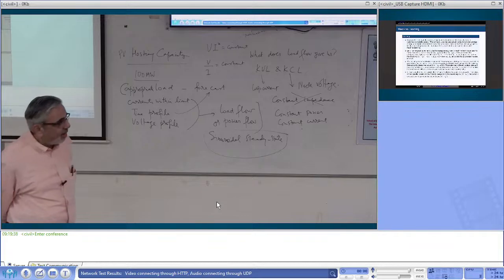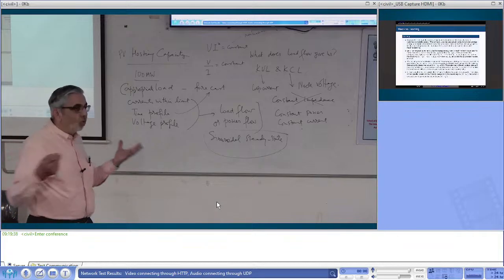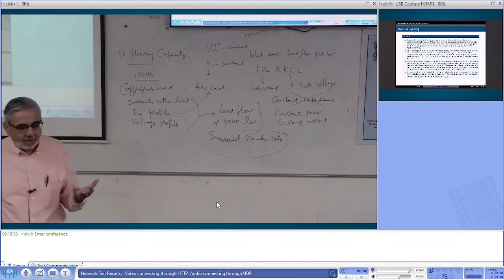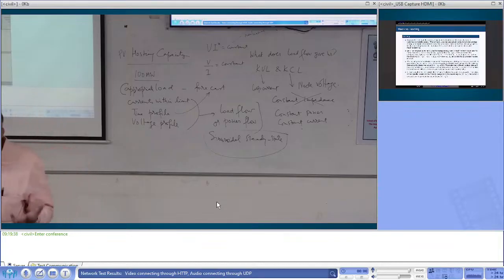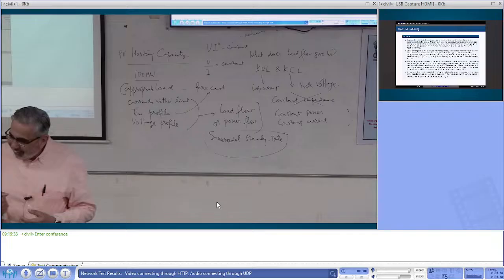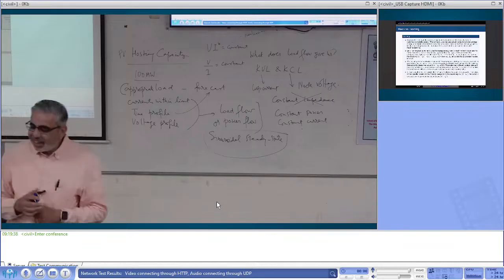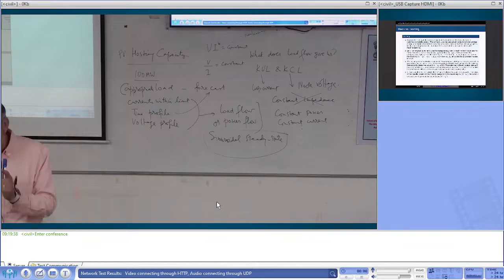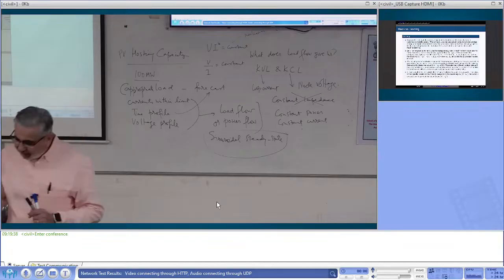That is true, but why multiple times? Like, why does a load flow have to be done thousands of times? What are the things which change? It's a power system, a dynamic system. What are the things that are changing? Load is changing, and phase angle, you caught that well. Phase angle, yeah, you are right, because unless you change the phase angle, you can't change the power you push. So load is changing 100%.